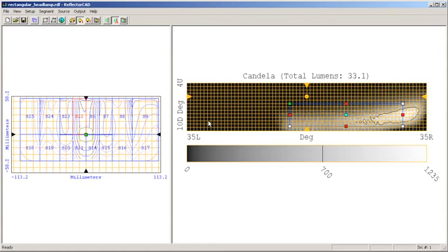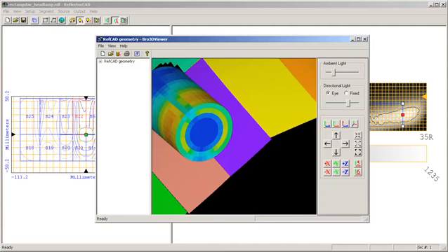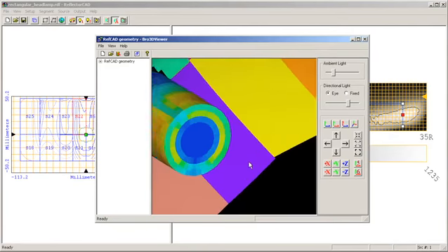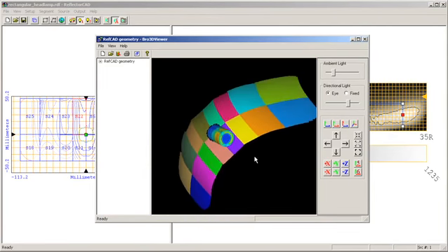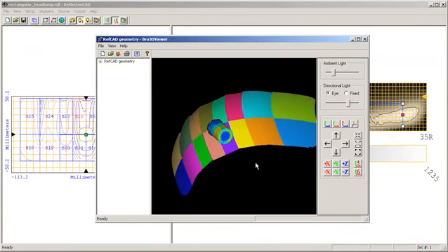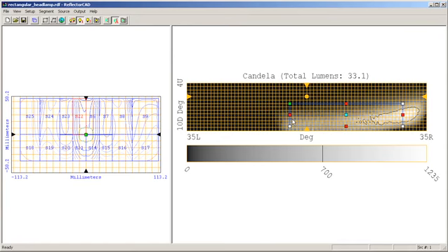ReflectorCAD will also automatically fill in the spaces between segments with inter-segment fillers and allow you to 3D visualize the reflector, source, segment shadowing, and inter-segment fillers. The resulting reflector segmentation geometry, including inter-segment fillers, can be directly output to ASAP for further detailed engineering design and analysis, or to an IGES file for use with the CAD package.